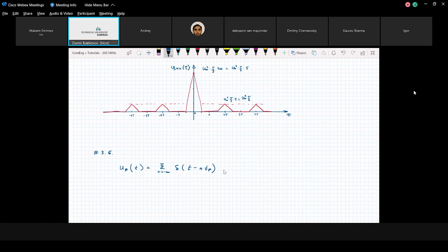And you see that here we start talking about power spectral density, because if you take this infinite sequence and try to calculate the energy, it's infinite, because for one delta pulse the energy will be 1. But then you have infinitely many components and no limit. But if you divide by the period, then you have finite power, and you can express all these parameters in terms of power. No problem.